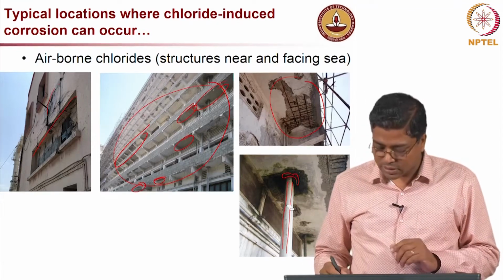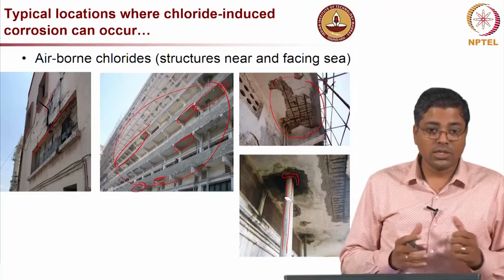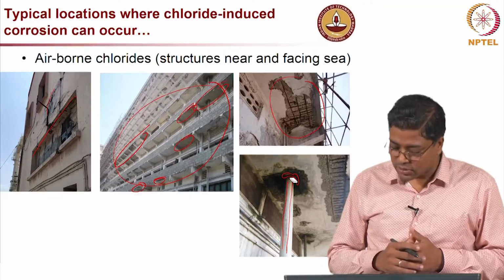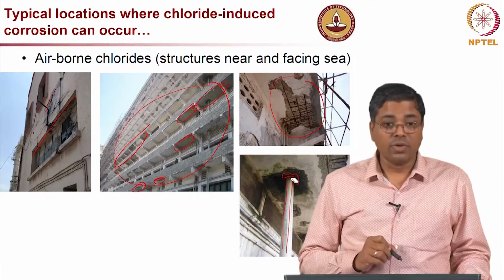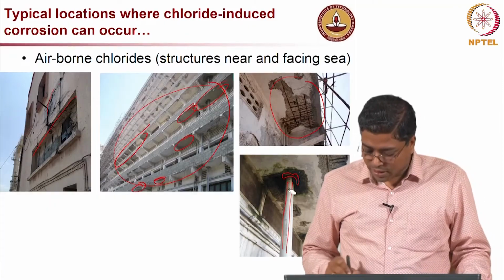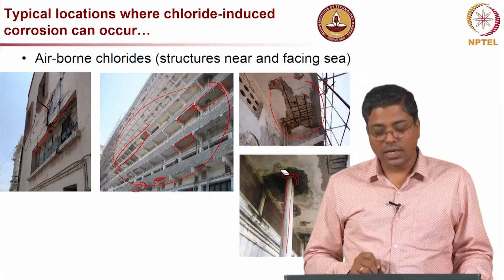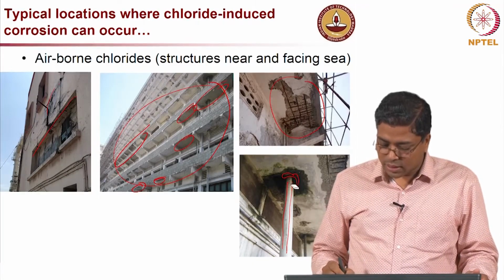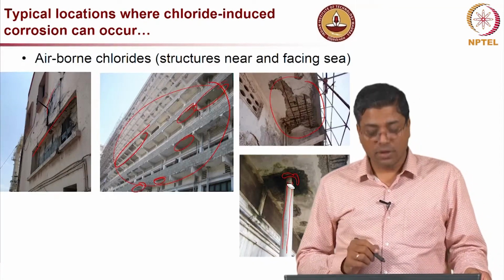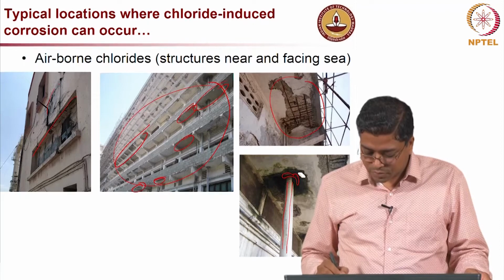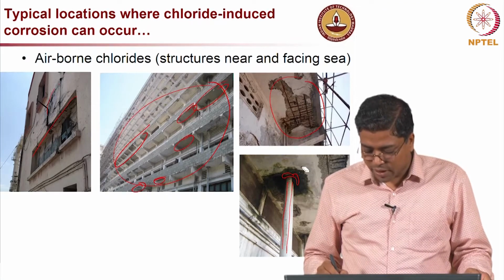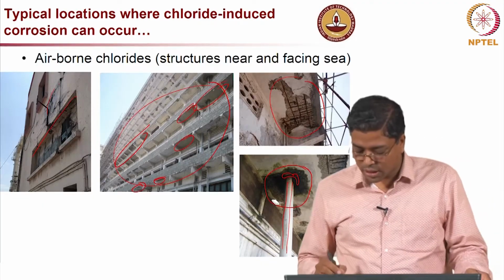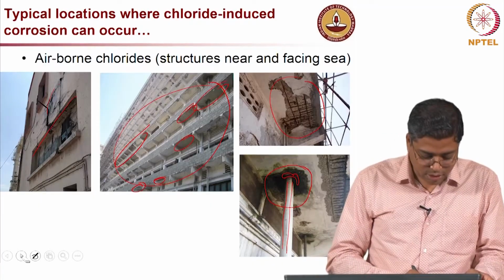So, this drain pipe does not have any space to move, which leads to breaking or cracking of the drain pipe, especially if it is made of a brittle material. So, we should think about those aspects also and try to provide some cushion here, so that the pipe will not be broken when there is some movement, and in that way we can prevent moisture ingress into the concrete around the drain pipes.